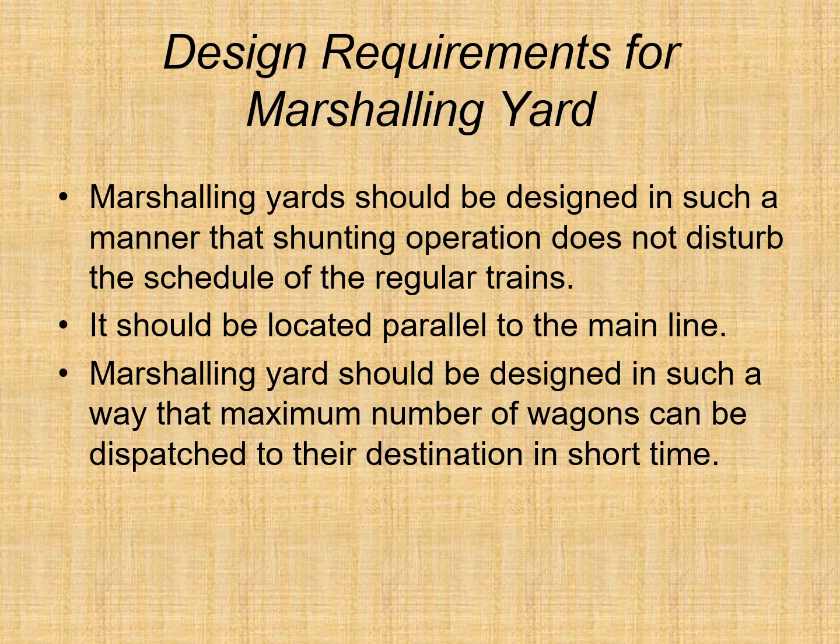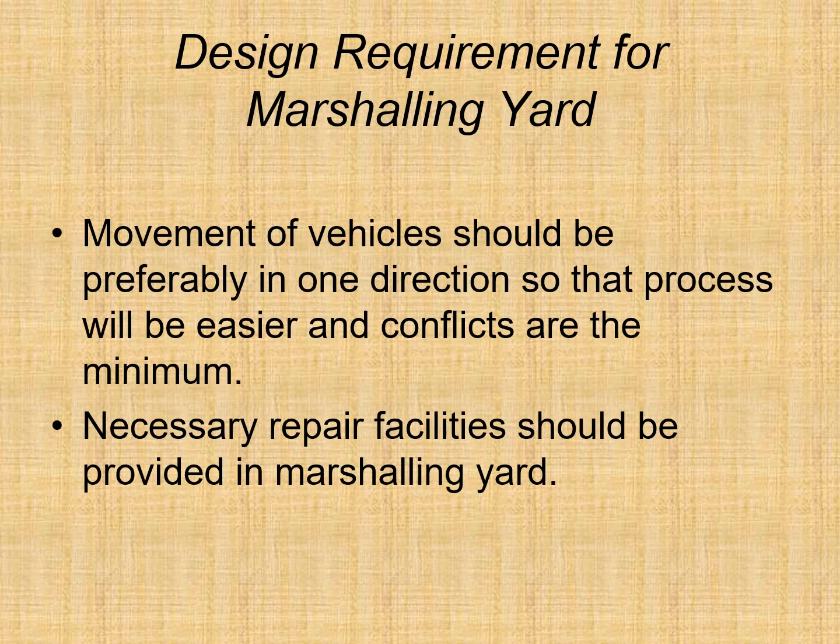Marshalling yard should be designed in such a way that the maximum number of wagons can be dispatched to their destination in short time. Movement of vehicles should be preferably in one direction so that process will be easier and conflicts are the minimum. Necessary repair facilities should be provided in the marshalling yard.